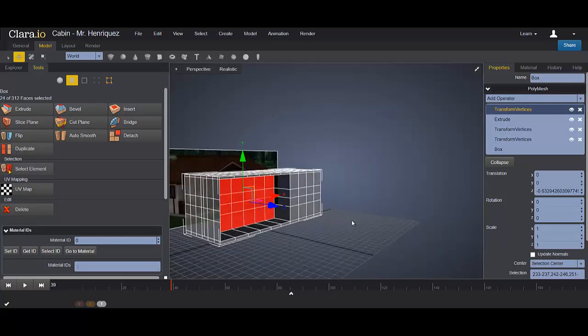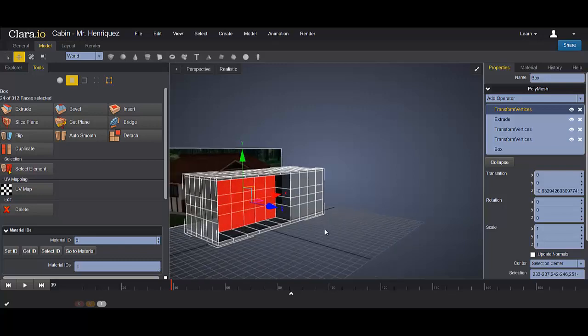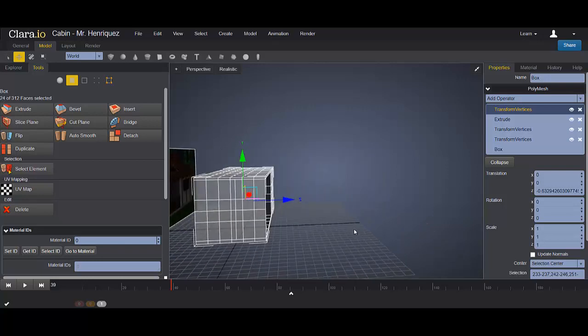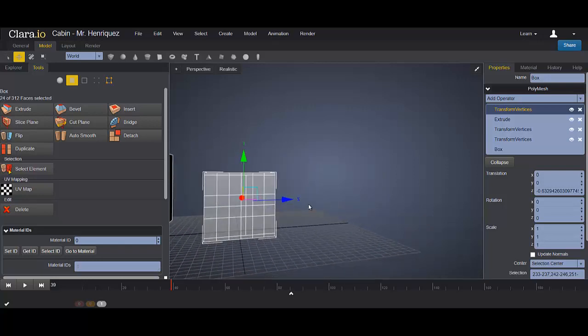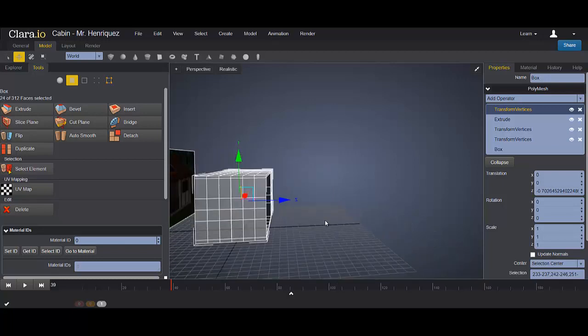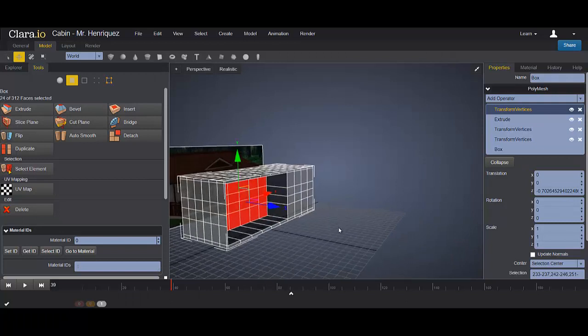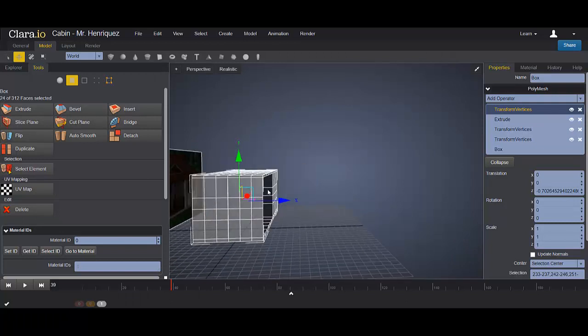And then now what I'm going to do is delete these faces. I don't need them. See? Make sure you align. That way you can perfectly delete those edges. So I'm aligning this wall with this line right here. So now I can just go and select the faces.